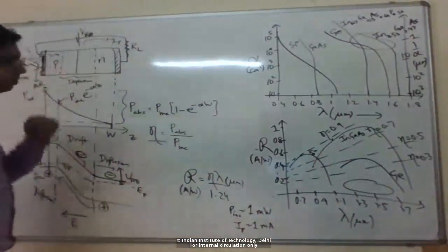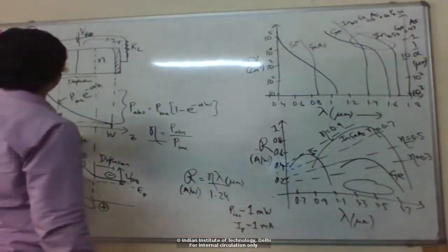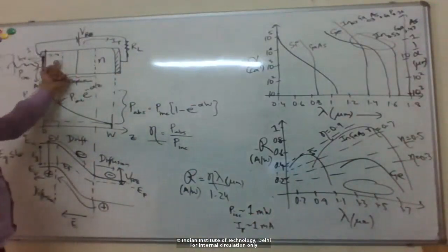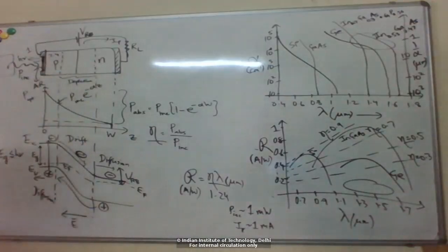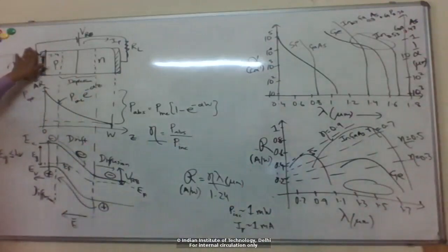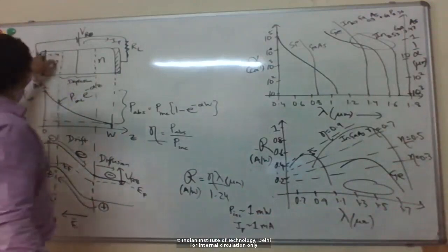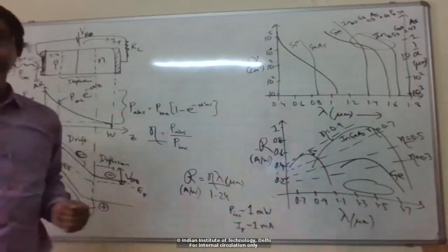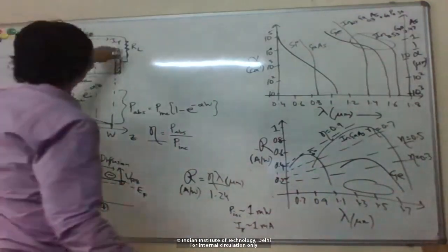And typically, we study noise mechanisms in these photodetectors in some detail. But one thing that happens is that because you have carriers here already because of this doping, right? There is what is known as dark current. Okay, so even if I block the input to the device here, there is no light incident on my device. Even then, there is a very small electric current flowing just because there are some carriers here and some thermally generated and excited carriers which have some kinetic energy, right?